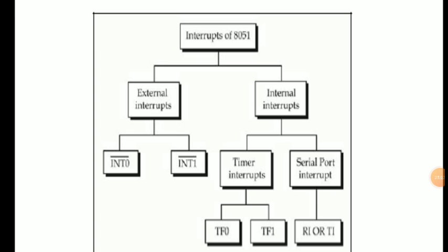Now just look at this diagram. Internal interrupts of 8051. External interrupts INT0 bar, INT1 bar. Internal interrupts: timer interrupts and serial port interrupts, TF0 and TF1, and the serial port, that is RI or TI.